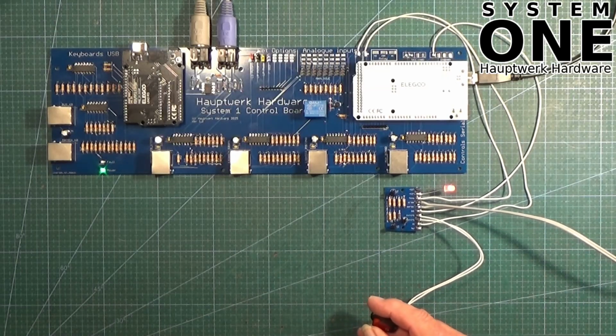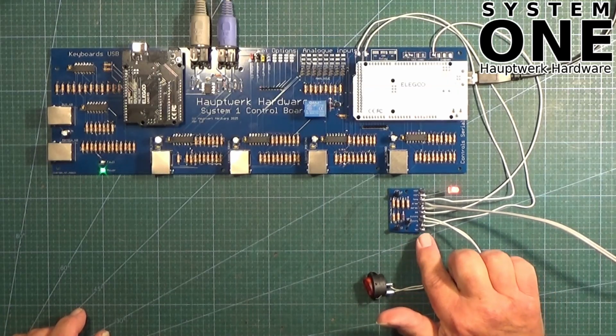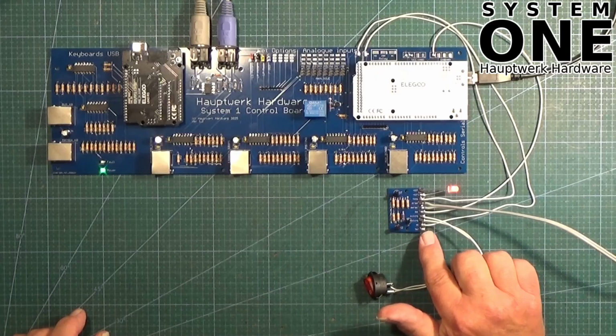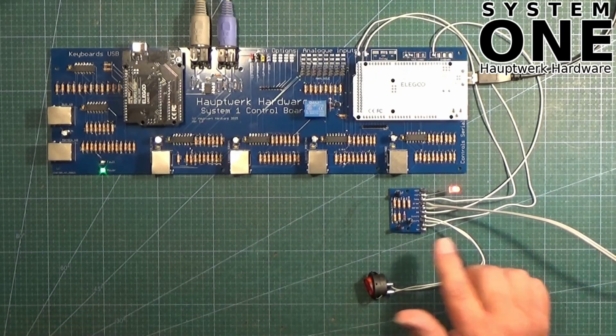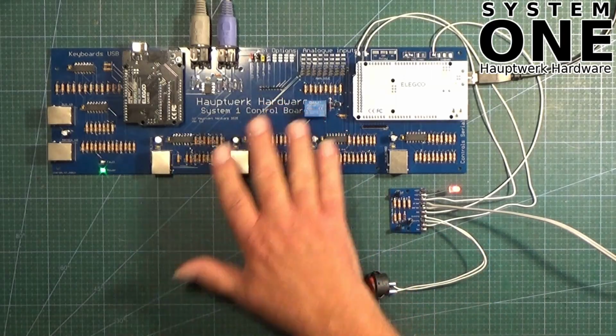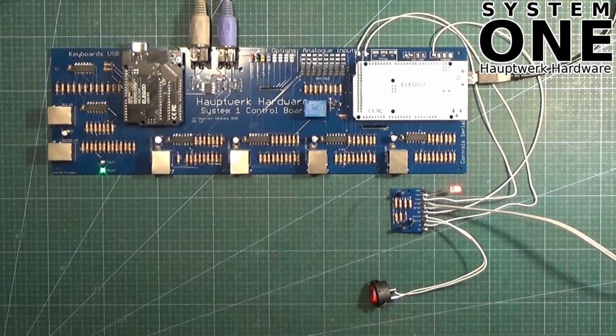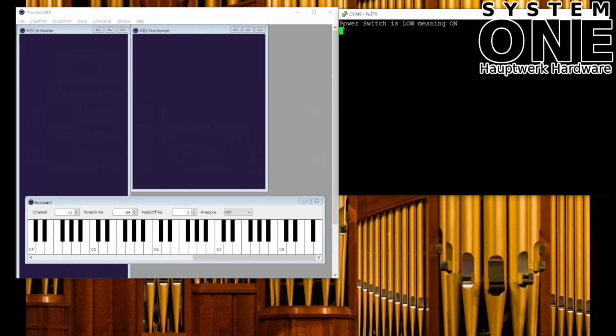When I do, nothing really much is going to happen, because all this would normally do, as we saw, is pull this control connection, which is not connected right now. This is the green lead from the power supply. Switching this on pulls that low, but also the control board knows that we've switched it on. So if we turn that on now, and we look at the computer, we can see that the control board has seen that, and it says power switch is low, meaning on. But we can also see that it hasn't sent any MIDI. There's no MIDI come out from the board at all. It's just noticed that we've turned the switch on.